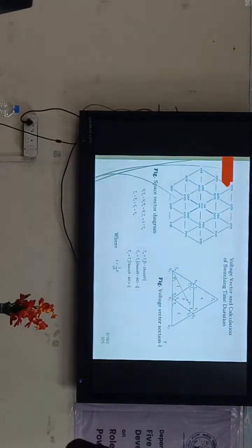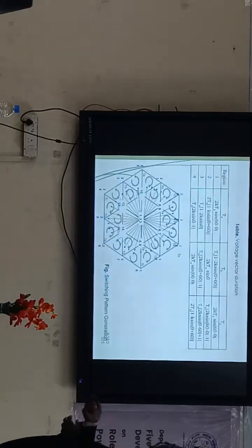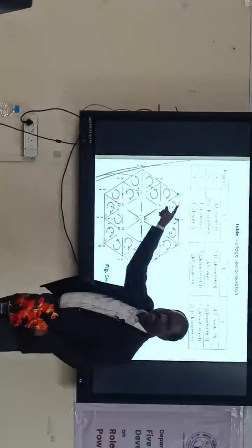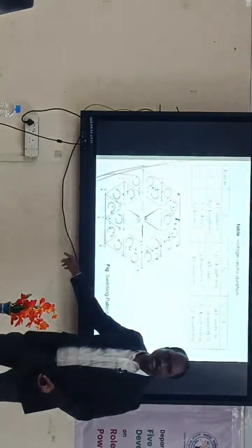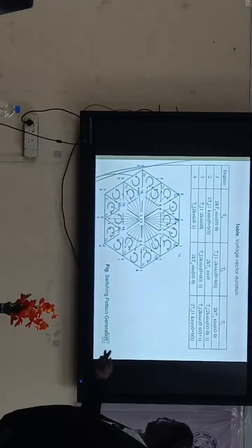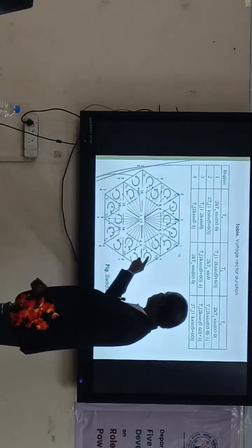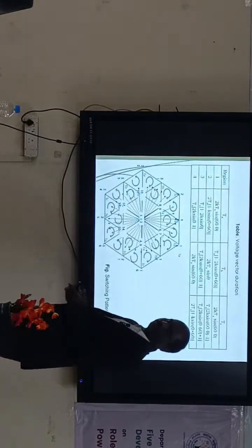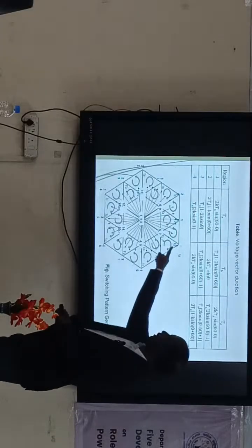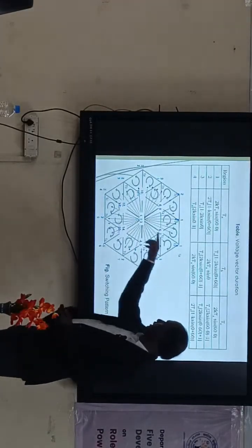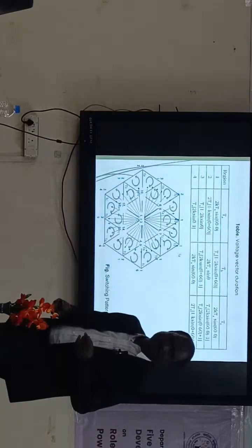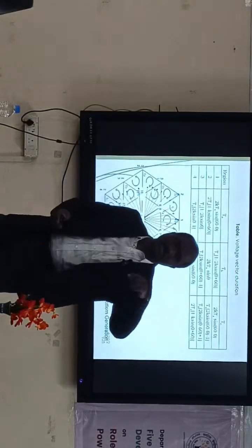Where is your implementation of this vector? Okay. If you follow that, you see here, these are vectors. 1, 2, 3, 4, 5, 6, 7, 8, like that, we are going to have 48 samples here. So your switching frequency is 48 into 50. This is the switching pattern. One sample is clockwise, the second sample is anti-clockwise, clockwise, anti-clockwise, like that we have to implement that. Each and every switching state is given by some number, 1, 2, 3, 4, 5, 6, 7, 8, like that, 26, 27, 16. Because our control has to recognize, each and every switching state is designated with some number.